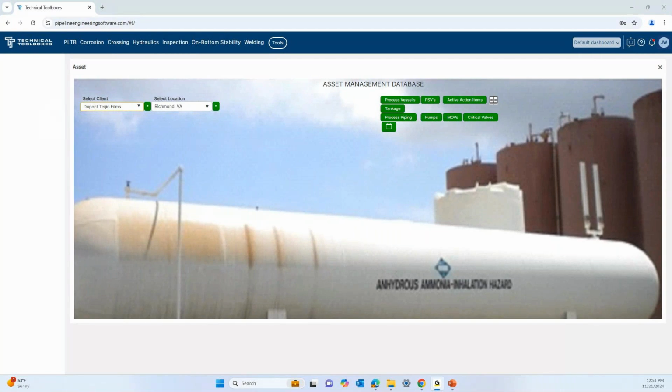Okay, and that does happen. It's very rare, but you'll just have to go to that particular code, the ASME Section II Part D, and look that up. The fields are open fields, so you can put the material in there, the stress value per temperature per year built, and all that. You just have to go look it up. There is a means to add to that if you request a certain spreadsheet and fill out the information needed for it. We can add that as well.